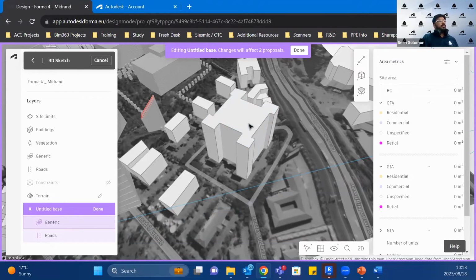It kind of speaks to what Forma was created for and how it works. In the past, to do a site analysis, you used a lot of 2D images. You would take a 2D image and see what the sun direction was and so on. So in a case like this, you would start off in Forma because you can then demarcate the site extent, and you can see already what the conditions of the sun are. What direction is the sun moving in?